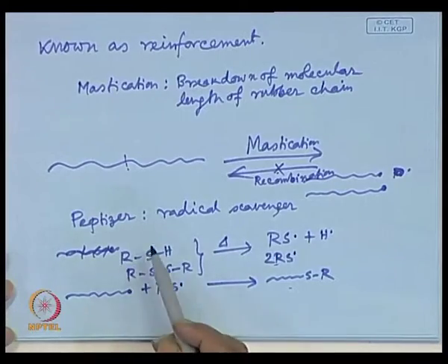A rubber mill may be as wide as the breadth of this room, and its height may be beyond the ceiling. For rotating such big rotors with high viscosity polymer, you can understand how much the power consumption is. So, saving that power for 3-4 minutes in one batch is a very big thing, saving a lot of money. For that purpose these peptizers are used.